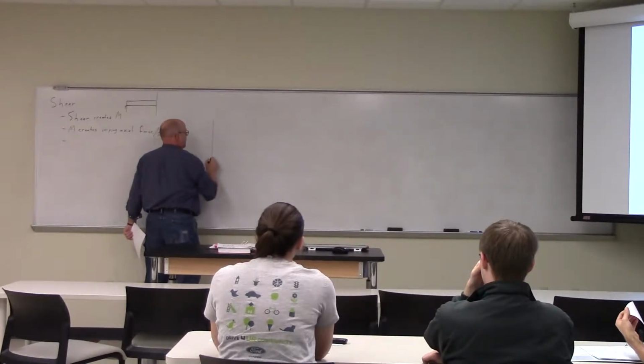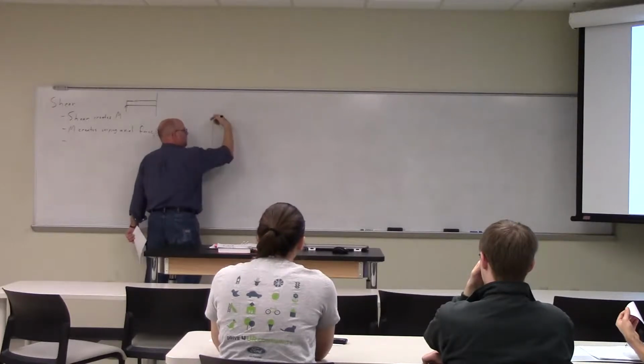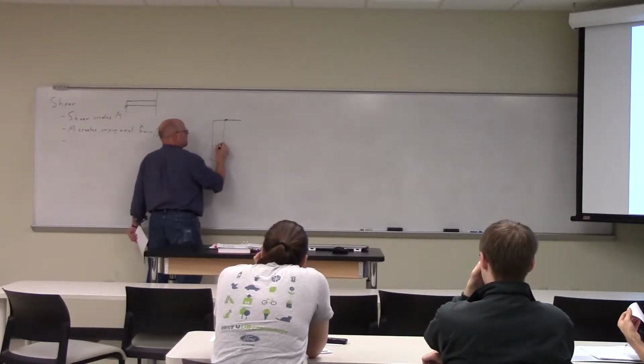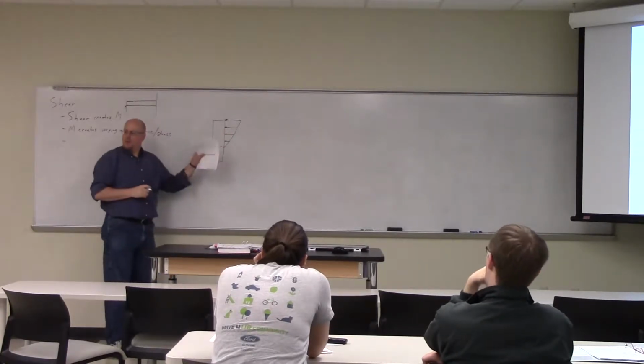If you remember, I did a sort of side view of this specimen. I'm squeezing it up like this, there's a big force pushing up here. Here's my neutral axis, maybe about a third. There's a big force there, there's zero force here, and there's less and less force as I go down. You remember that?